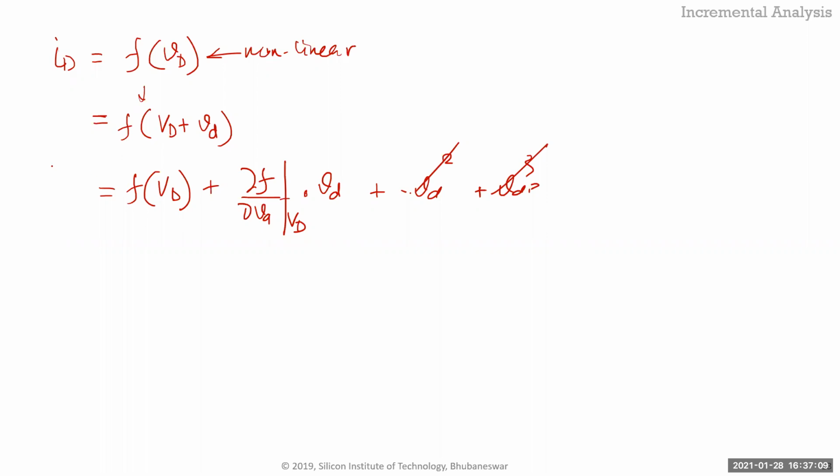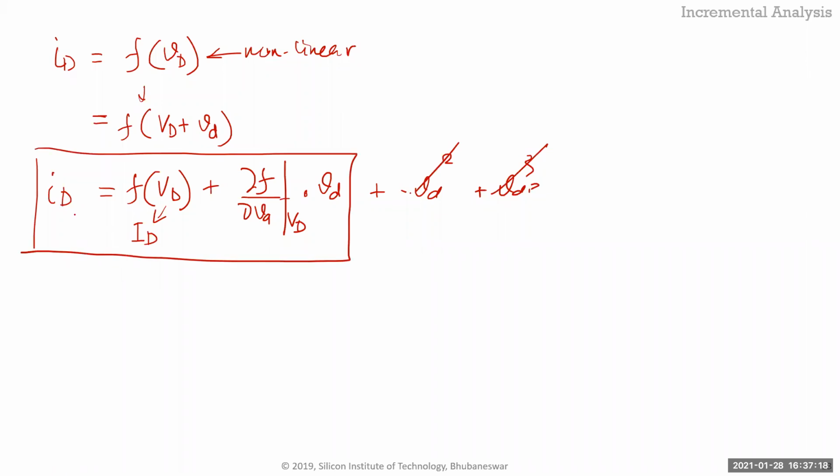So that's, in terms of your diode equation, basically what you're saying is that for very small VD, you have the DC portion, and then you have the linearized part, which is basically the linear term of your Taylor expansion, which is the same as your slope. So derivative actually means that, it's the first term of your Taylor expansion, and double derivative means the second term, the coefficient of your Taylor expansion.